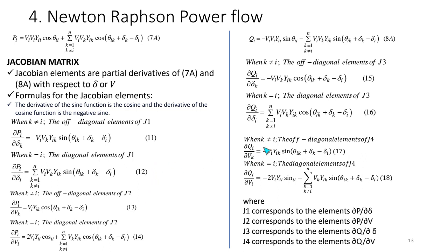Clear? Okay, then move on to the next one, on the right side of the slide, which is reactive power. The reactive power that we discussed on the previous slide, written as 8a. I just captured that equation as it is from the previous slide. What we're going to do is take the partial derivative of reactive power Qi with respect to delta k.